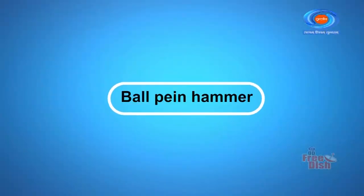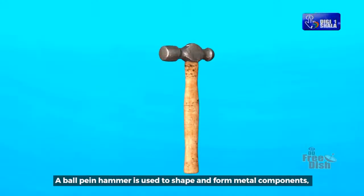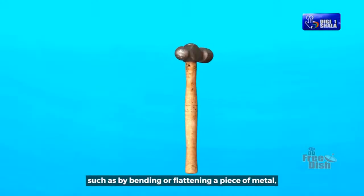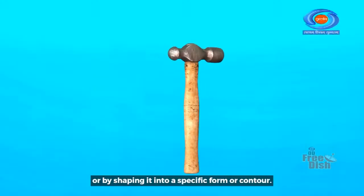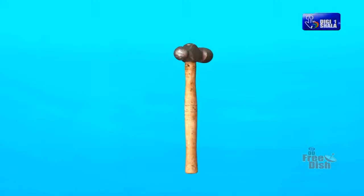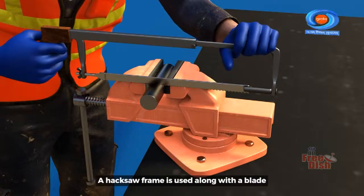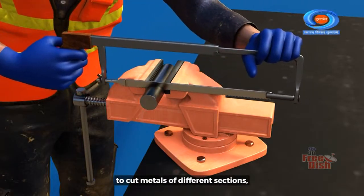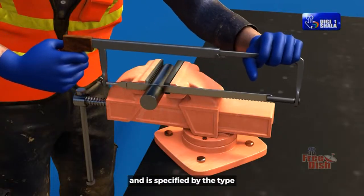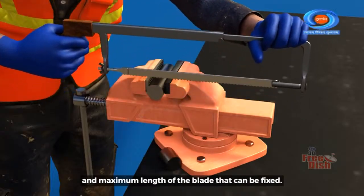Ball peen hammer. A ball peen hammer is used to shape and form metal components, such as by bending or flattening a piece of metal or by shaping it into a specific form or contour. Hacksaw frame with blade. A hacksaw frame is used along with a blade to cut metals of different sections and is specified by the type and maximum length of the blade that can be fixed.